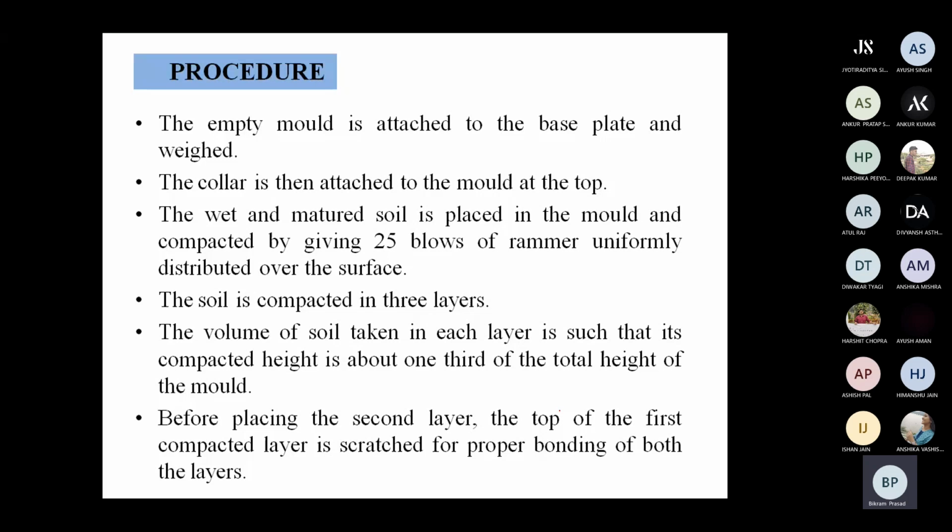Generally 2.44 meters is the height of the shuttering boards, so casting is done up to 2.44 meters, and then we provide the joint at that place, and again after some days when it is hardened, we pour again. When the pouring of the concrete is done, we properly clean that surface. If there is any debris, we remove it, and only then we pour the second. A similar concept is there. We have to scratch it properly so that there will be bonding.